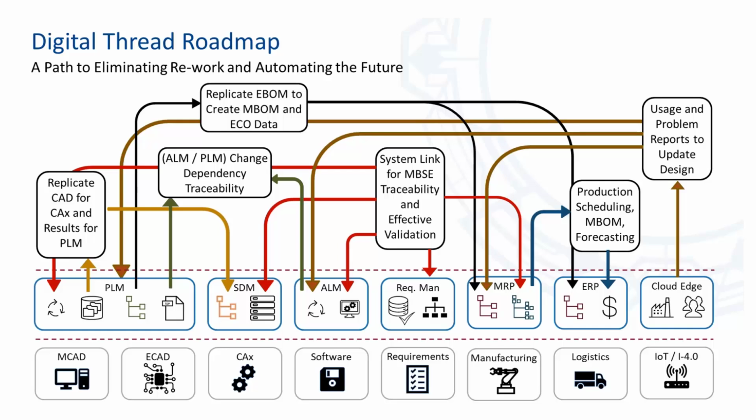So it could be that an MES system or an ERP system is taking that EBOM and creating that, possibly with routing information and process planning and things like this. So that's number one. After that, you might have different types of integrations like simulation data management for analysis with PLM. That system's going to require that there's binary data replicated. So you might need to take that engineering binary data, replicate it into your simulation data management so you could run analysis, and then maybe feed back to the original designer some results and reports on that analysis so they can incorporate that within the design itself.